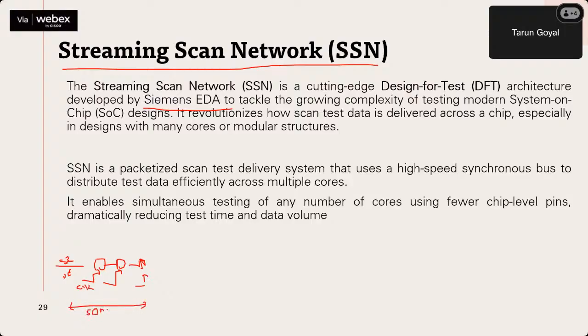If you talked to me a couple of years back, we call it the shift frequency. How long the chains are, and these cycles in which we are bringing data to the device and then shifting out. So this is multiplied, and once we convert into ns, that's translating into the test time. So this 50 megahertz is basically 20 ns.